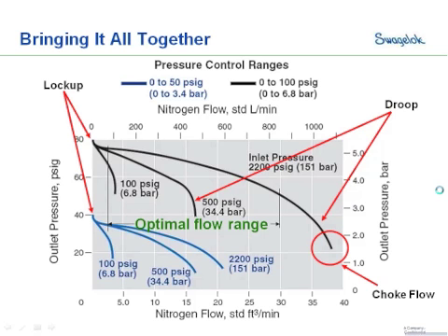It's going to affect the resolution of the regulator that we looked at earlier. You're not going to have a whole lot of adjustment that you're going to be able to make on the regulator. You're probably going to find that your handles turn fairly far in on the regulator. And it's really probably not going to be giving you the type of performance you'd like to see. So it's much better to be able to size those regulators for that optimal flow range.